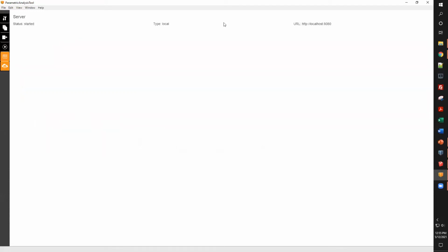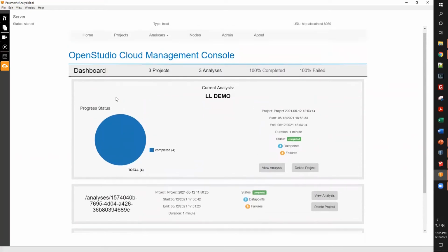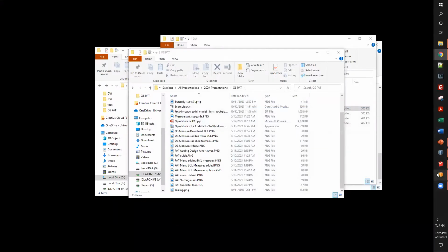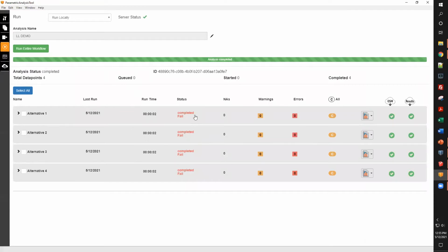And again, this is the server. I like to bring it out in the HTML page just because you're not really able to access that quite yet when you're running the simulation. So it'll give you a little more information ahead of time. But typically, if you're running your sim and the status doesn't change, it says starting up and just says NA, then you likely have a compatibility issue with your OpenStudio results measure, which is why it's not running properly.